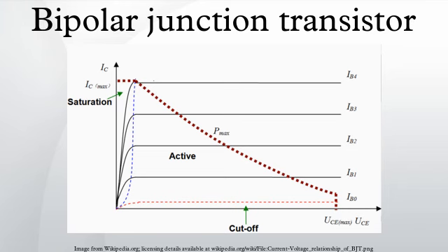Active mode PNP transistors in circuits. The diagram shows a schematic representation of a PNP transistor connected to two voltage sources. To make the transistor conduct appreciable current from E to C, VEB must be above a minimum value sometimes referred to as the cut-in voltage. The cut-in voltage is usually about 650 mV for silicon BJTs at room temperature but can be different depending on the type of transistor and its biasing.